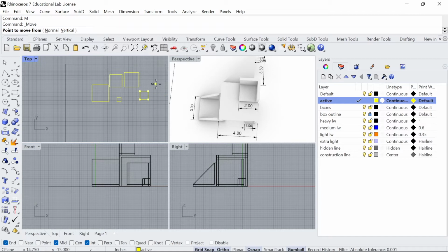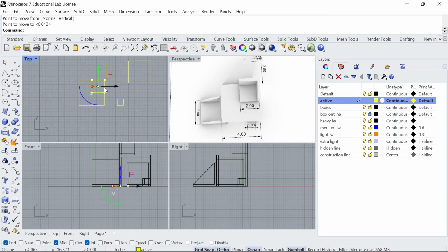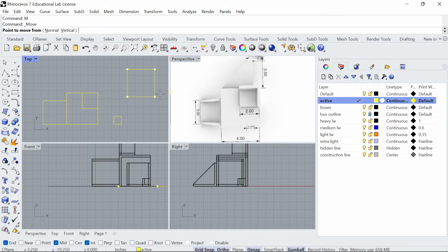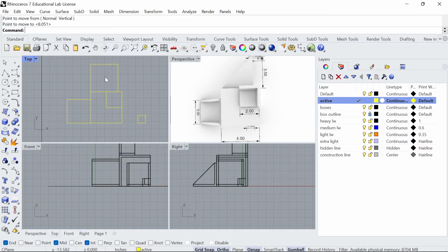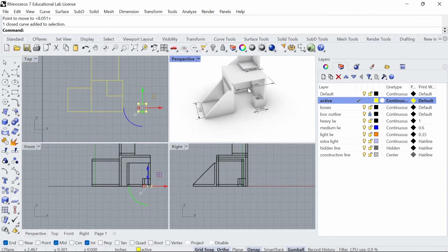So this thing, if I'm looking at the 3D view, or in your case, whatever's in front of you, you know that this is situated right here relative to the 4-inch box. Okay. And then the 3-inch box is to the left of it. So I'm just going to go ahead and move this to the left of it, the bottom left-hand corner of the 4-inch box. And then finally the 3.5 inches. Looks like it's situated to the left inside of the 4-inch box like that. Okay. And none of this is 3D. It's just 2-dimensional lines to represent what we see as orthographic flat drawings. Okay. And orthographic means they're scaled. They're not perspective. So 4 inches is 4 inches in measurement. And then finally we have this 1-inch box, which is inside the 4-inch box. And you notice that there's a thickness.